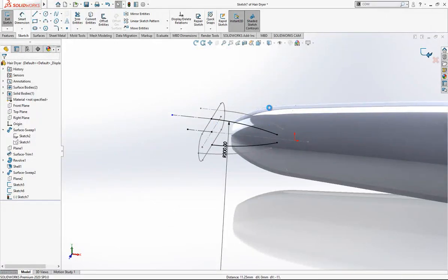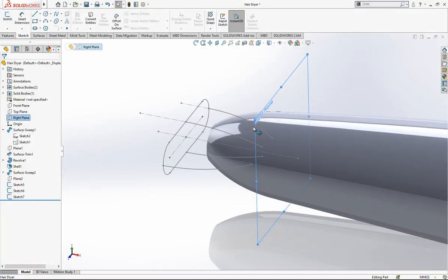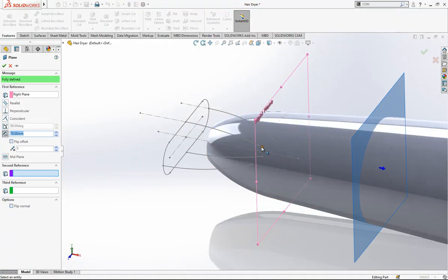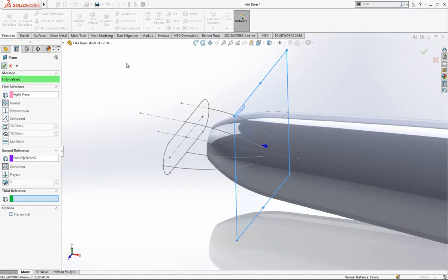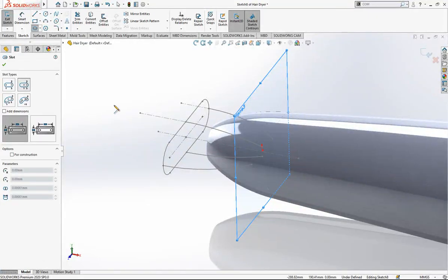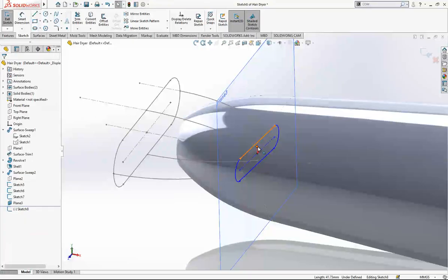What we are going to do now is create another plane and then put a slot there. We have 4 points. It is good enough to define a slot, and I will just pick a slot. I will just place it somewhere here. Firstly, I'm defining this point.